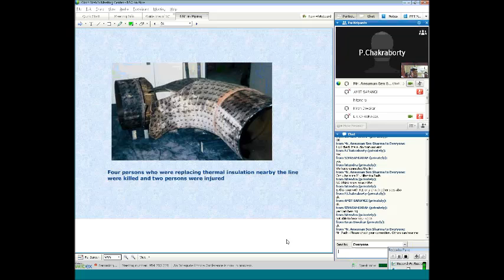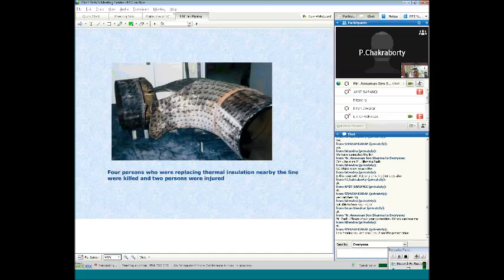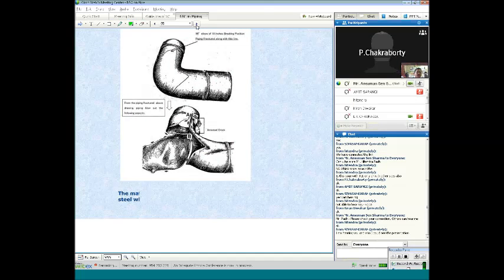So what happened is EPRI started looking into the matter, and they started investigating the cause of the accident. When they took a closer look at the location, this portion was actually affected. It blew out like this. The nominal material thickness was 12.7 mm, and the thickness was reduced to almost 1.5 mm near the rupture zone.